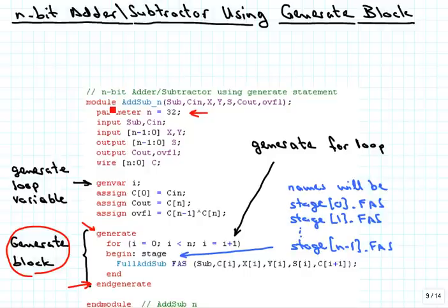The beginning here of the module is just the same as it has been for other modules. We give it the name add_sub_n because we can do this for an n-bit adder subtractor. Then there is the subtract add control variable here, and just to remind us again, sub is going to be equal to 1 for subtract, and it's going to be 0 for add.